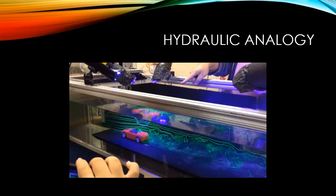But here in hydraulic analogy, what we are going to discuss is only these high speed flow models. So what are the high speed flow models which are considered? What are the major applications also? Applications are transonic unsteady flow past wings, transient phenomena in high speed flows, and shockwave interaction. In all these cases hydraulic analogy will be there.